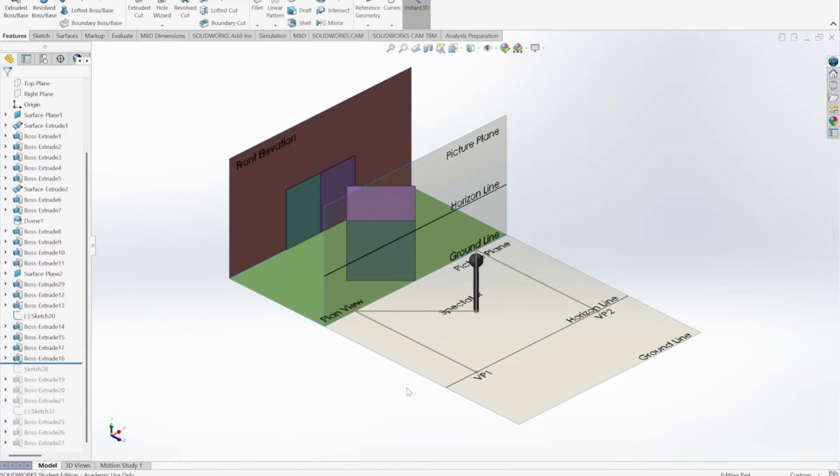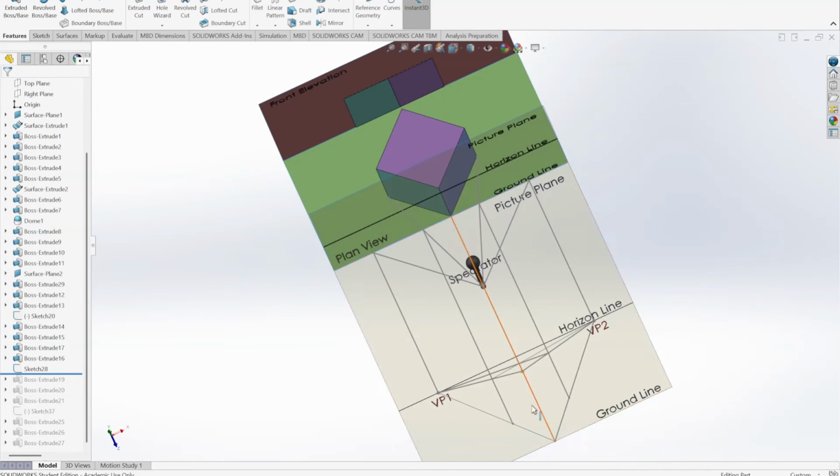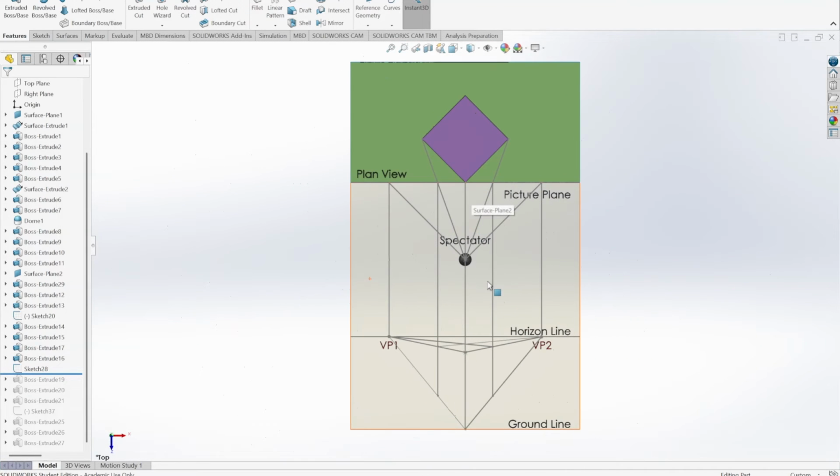So the next part, I'm going to showcase this, and it is going to have quite a lot of drawing here, but we'll go through it step by step in the animated PowerPoint as well. We are going to essentially draw the drawing in perspective here. So let's have a look at it down in the plan view. What we did here is we have our letter M. So we've got our vanishing parallels, we brought them down, and we located our vanishing points.